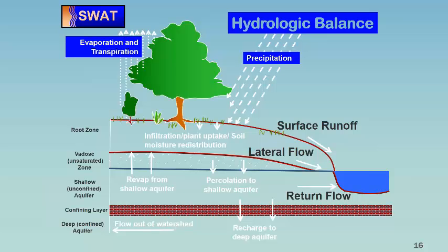Okay, SWAT handles only up to the shallow aquifer. We do not keep track of water that goes into the deep aquifer. So if you really want to know more about your deep aquifer processes and you need a true groundwater model simulation, SWAT has been successfully linked with another public domain model, a USGS model called MODFLOW. We have an interface and all the tools and technologies available to take any SWAT model and link it with the USGS model MODFLOW on the SWAT website, so you can read more about it and download the tools and documentation.